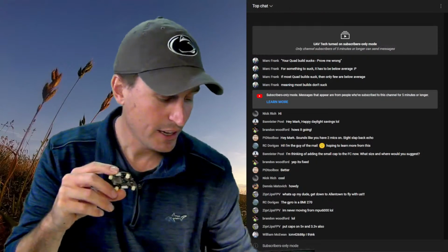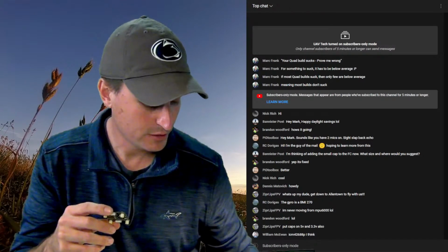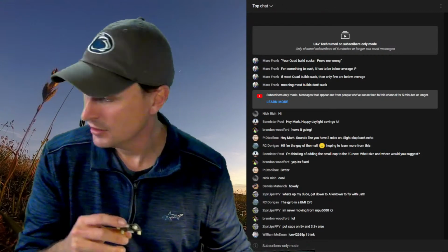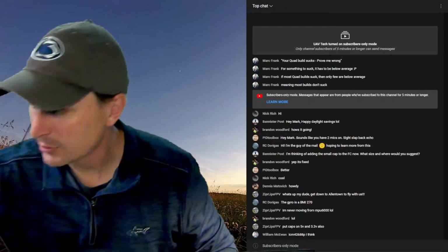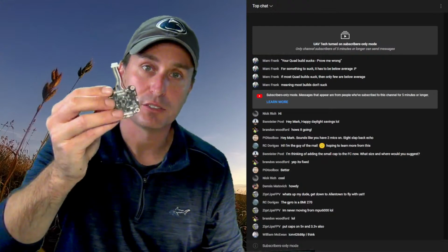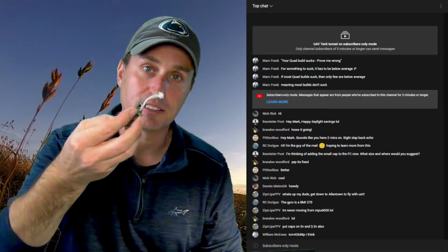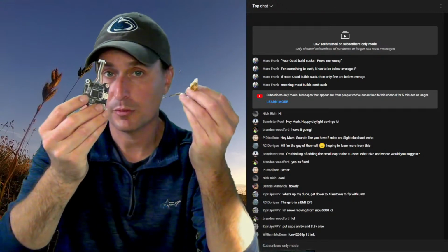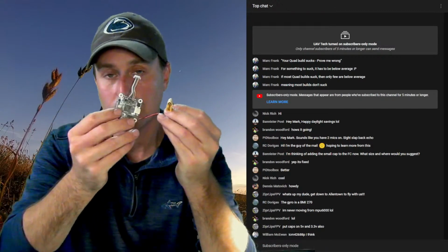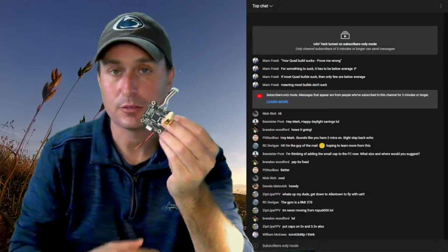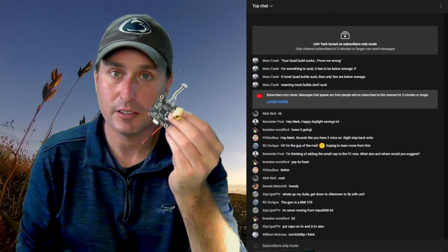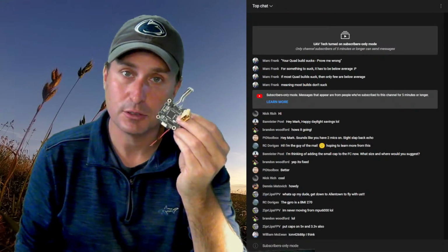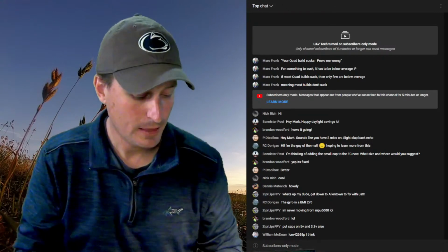I had this one on here. I don't know where it is. It's here somewhere. Yeah, I had this one on it, and it had the issue with the pitch axis. I wired it up with a separate battery source to power the flight controller like I just talked about, and it went away. So that's not a gyro issue. That's an electrical isolation issue.